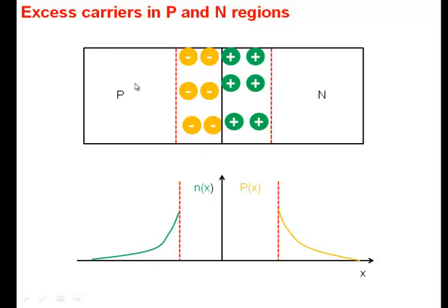Now, obviously, as I apply more voltage, more of these charges will get injected. So now you have these charges, which we can call QP and QN, that change in response to voltage, and therefore we have another capacitance, which is the rate of change of these charges with respect to voltage. We call that capacitance the diffusion capacitance.